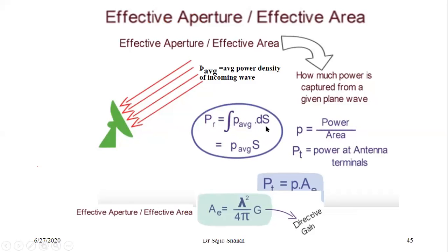From this we already calculated the total amount of received power. And this A is AE, the effective area, which is concerned with the receiver antenna. A is calculated using the formula A equals lambda square divided by 4 pi, times g, where lambda is the wavelength.